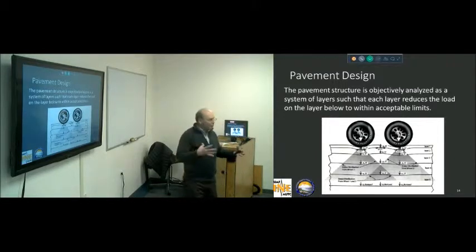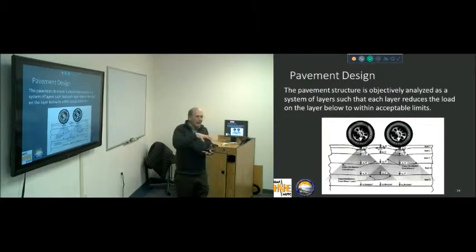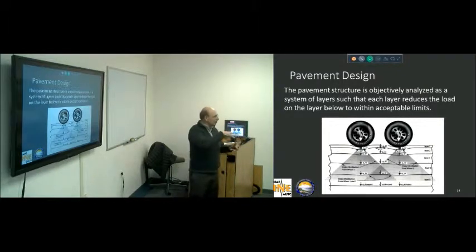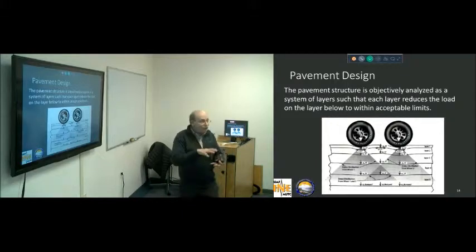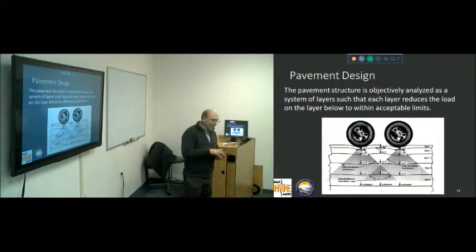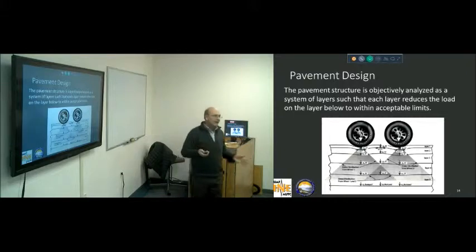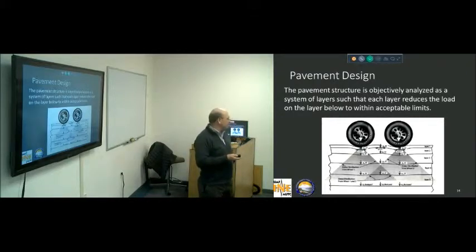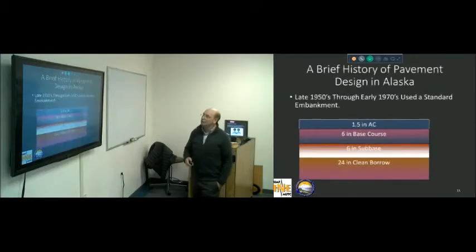So the idea there is we are calculating at the top of each layer the stress, and then we're making sure that that stress is low enough that we get the life that we intend to get out of it. And that's critical. So we have to know the materials to put in our equations to make it work, and we can't shortcut that. We really have to understand that. And all the research that I've ever done in the last 40 years has proven that over and over and over again. We have to understand those materials.